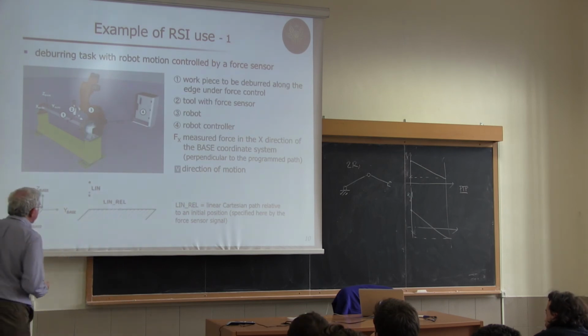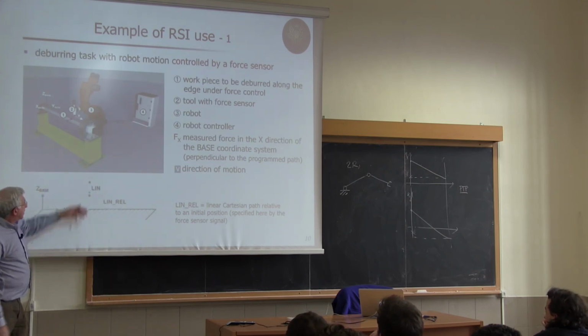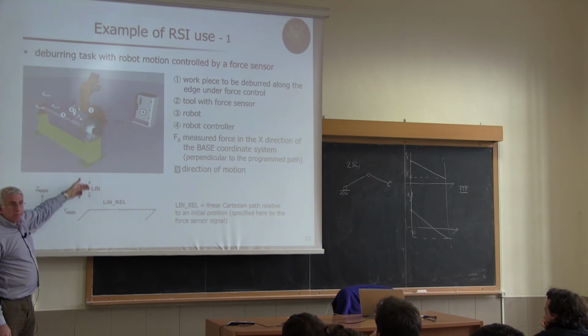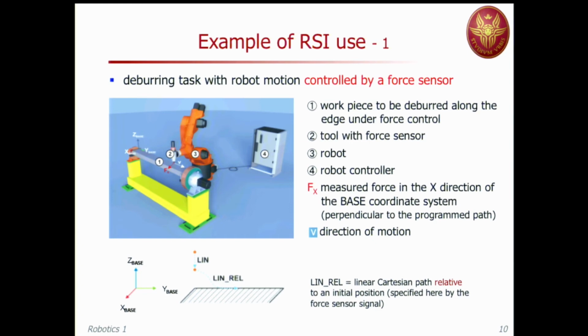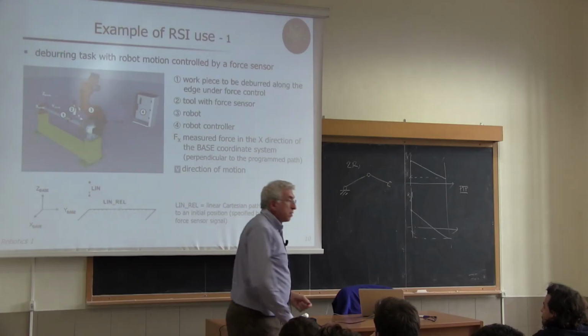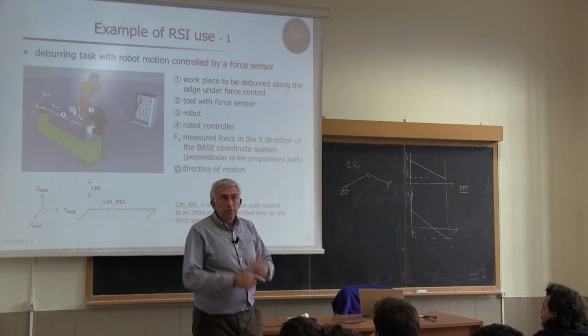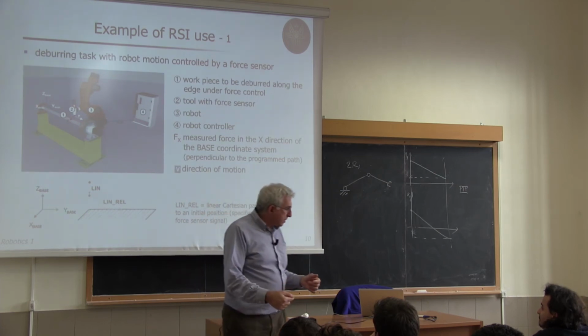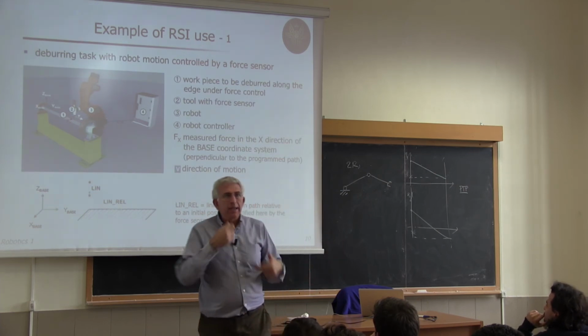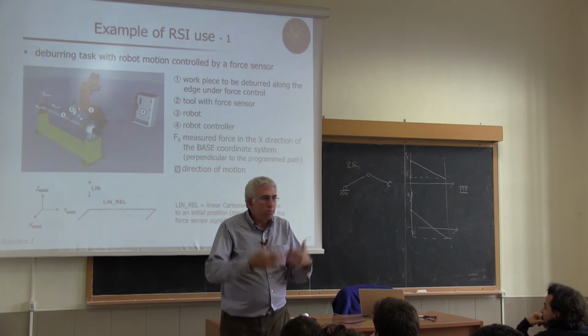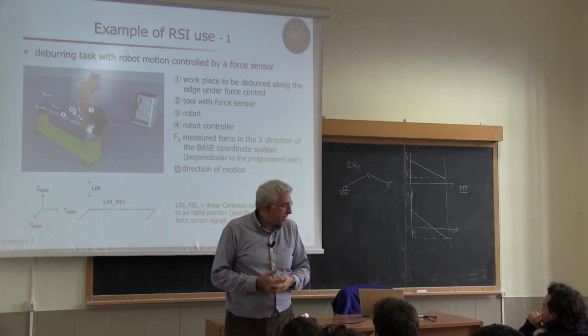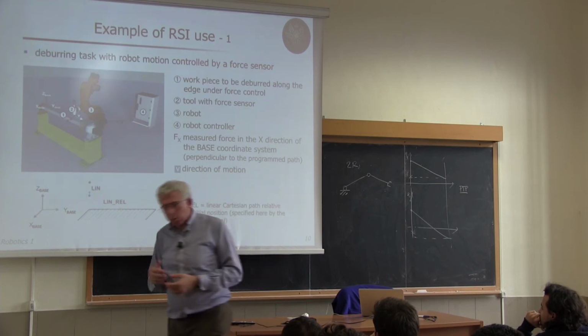So in terms of commands, it may be some linear motion commanded in order that the system approaches, and then a command which is relative, so you provide linear motion along the direction of the velocity v, relative to the fact that the force sensing in the direction x is providing some input of, let's say, more than 10 Newton, okay? And then you start moving.